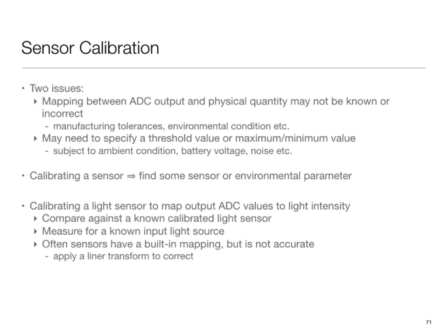But if the absolute value matters, like you're trying to get the north direction correctly, then you need the sensor output to be well calibrated. When the phone realizes it has gone out of calibration, it asks you to recalibrate, and that movement of 8 is a way of asking you to expose the phone to different patterns of the Earth's magnetic field, and somehow they make use of that knowledge to do the calibration.